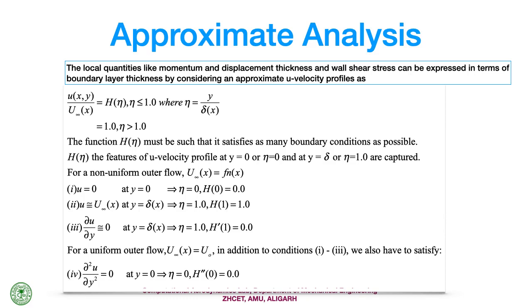The fact that this integral analysis is a very fast method for getting approximate predictions of the integral quantities. It doesn't bother about what happens inside the film, so it cannot give you the variation of the velocity profile, but you can suppose the variation of the velocity profile, and if you are able to suppose it correctly, then the prediction of wall shear stress, skin friction, boundary layer thickness at all x stations can be obtained.